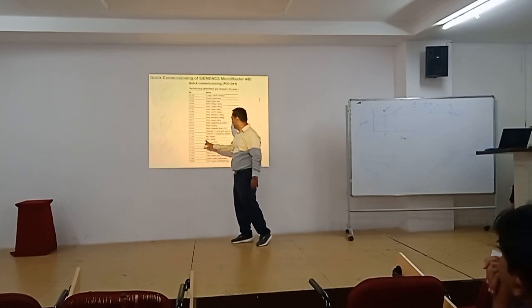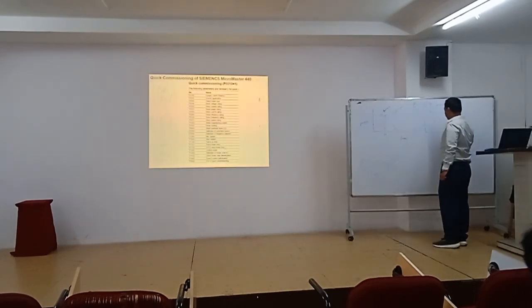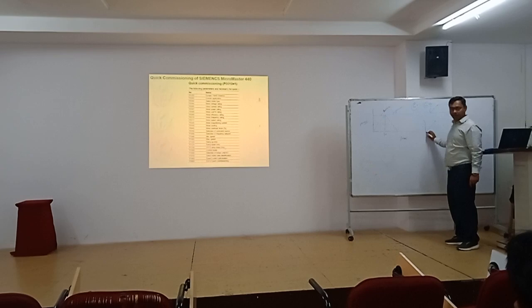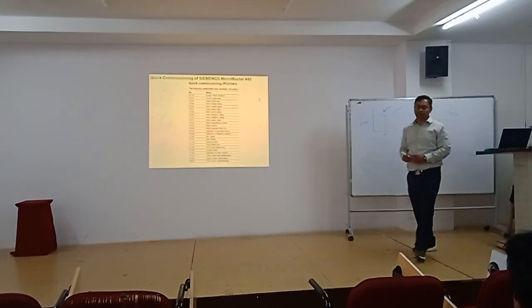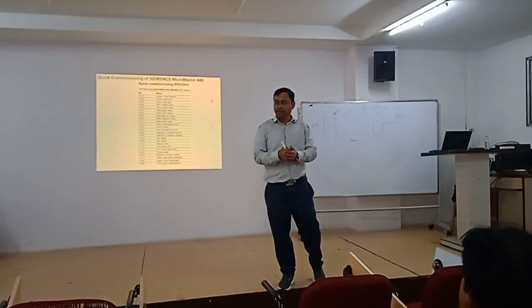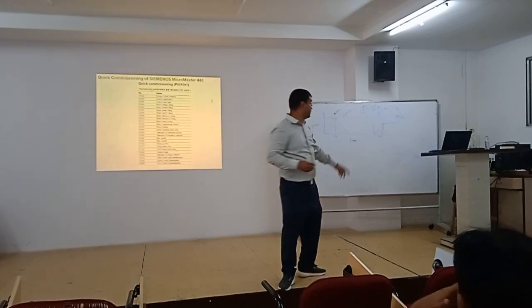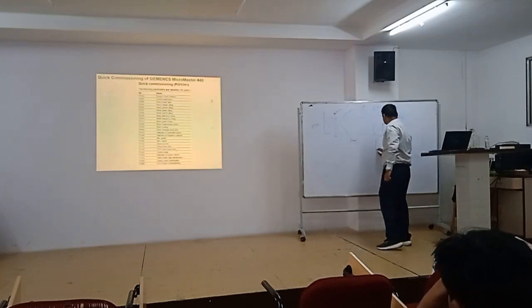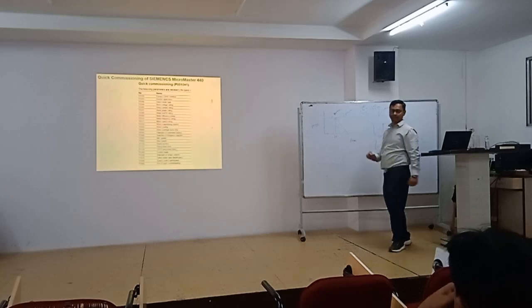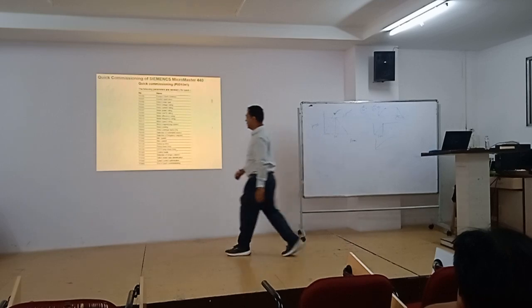1120 and 1121. That is the ramp-up time. So you start the motor, and after say 10 seconds it should reach maximum speed. Sometimes somebody may be traveling in, say, a patient lift in some hospital. In a patient lift, it's very smooth, it won't have any jerk, because they give more acceleration time. So you can set that time by using this parameter 1120.